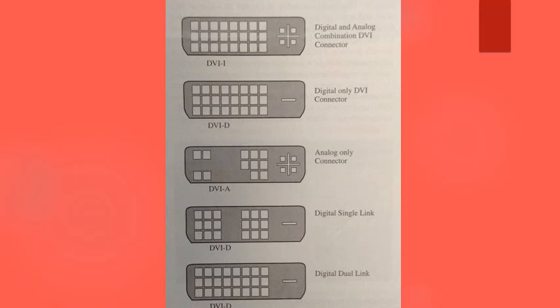The RF and F-type connections support the poorest quality video images and are found on the oldest technologies. The RF and F-type cables use standard coaxial cable made of a solid or stranded copper core conductor. The core conductor is surrounded by a thick insulator material. The insulator material is completely wrapped by a conductive mesh of foil referred to as the shield. The shield protects the core conductor from outside electromagnetic interference. RF and F-type cables provide the poorest signal quality transfer between supported home entertainment devices.